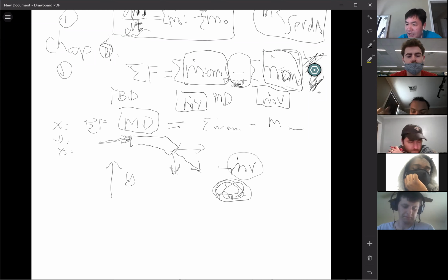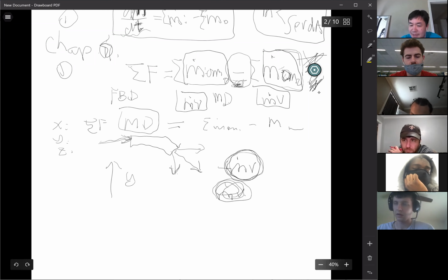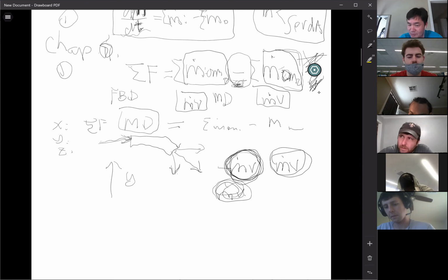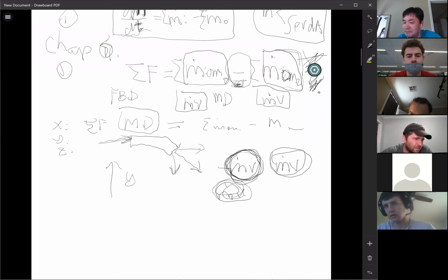And the easy way not to make a mistake is to calculate the magnitude first. Momentum magnitude is basically mass flow rate times whatever velocity you have. Don't use the sign when you calculate the magnitude. After you calculate the magnitude, put a sign in front of it to decide the direction. That will make it a little bit easier, right? If it's positive momentum, it's positive. If it's negative momentum, put a negative sign in front of it. Do the magnitude first, then place the sign.